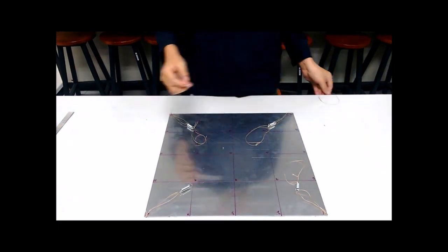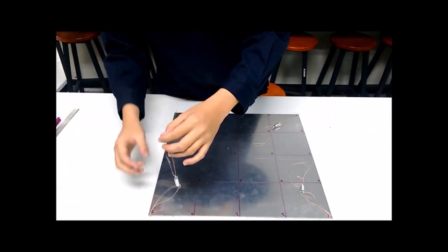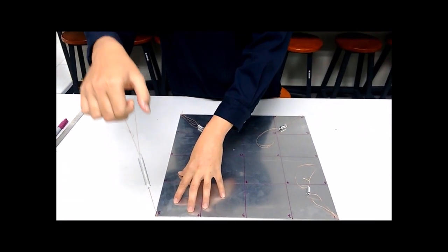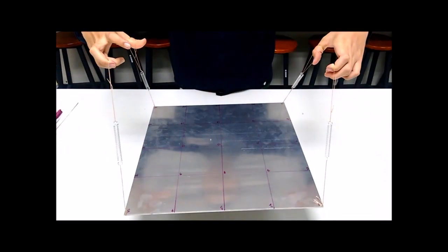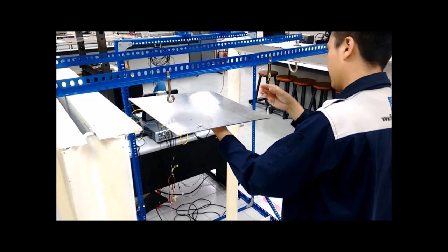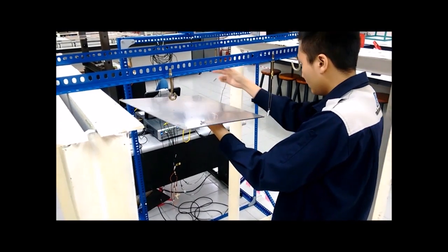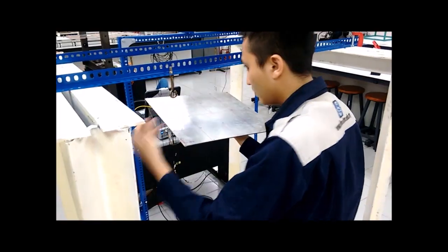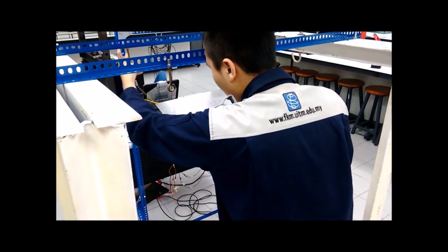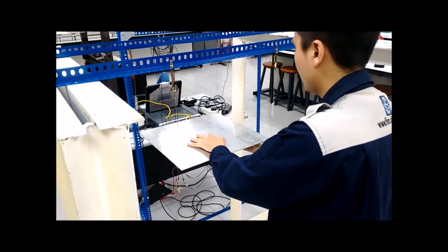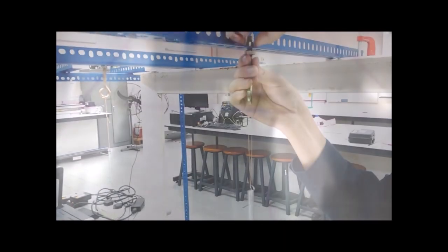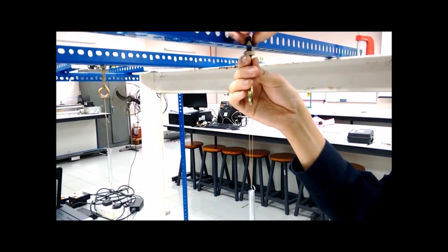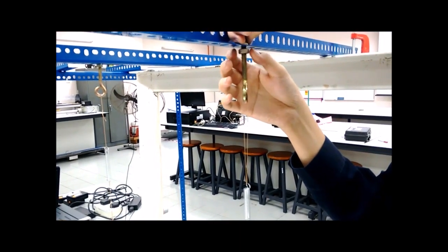This is because, in order to simulate the best free boundary condition, the structure must be able to oscillate freely when it is hung. After that, the structure is hung below something that is sturdy. This is to avoid any vibration introduced from the hanging pole while the experiment takes place. To ensure that the structure is hung in the flattest horizontal position, a water level is used. If the structure is not in a horizontal position, adjust the position and the length of the string at the structure edges.